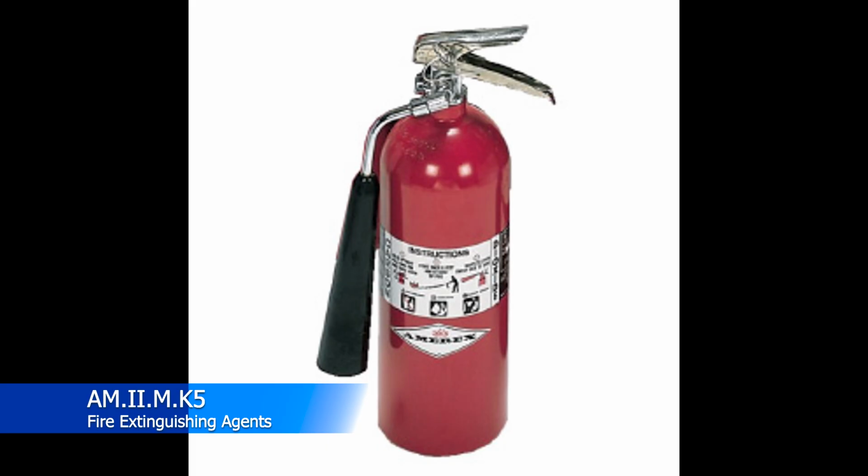So probably the first and the oldest of all the fire extinguishing agents is actually CO2. When discharged, it looks like a big cloud, and could potentially even look like snow as it enters the atmosphere. The idea is that you're displacing the oxygen around the fire, causing the fire to extinguish. You'll see these in some older aircraft, on recip engines and such, but generally speaking, everybody's moved away from it in the modern era.